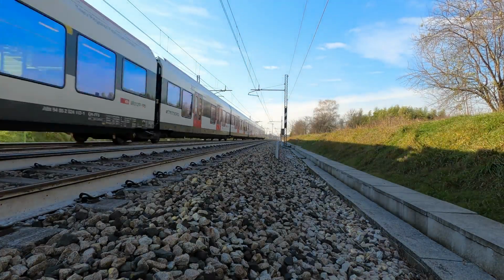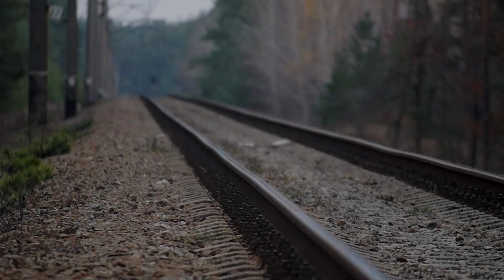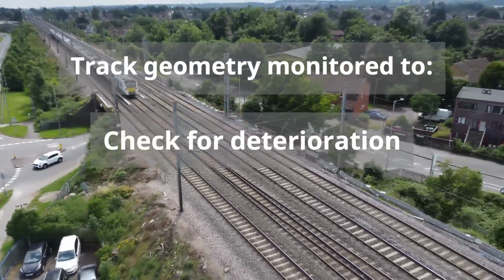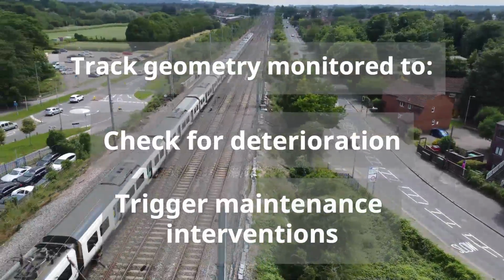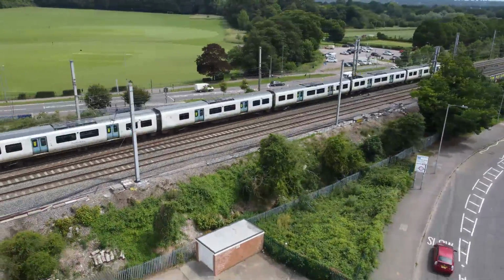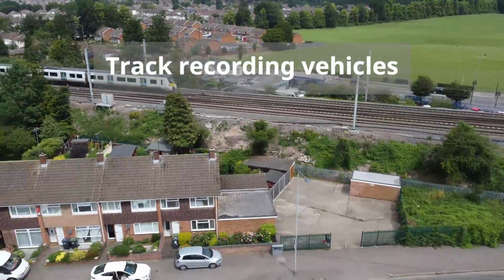Once the track has been designed and installed, that is not the end of the story. It then needs to be monitored and inspected as it's used by trains. It is inspected throughout its life to check for deterioration and to trigger maintenance to ensure it is safe for trains to use. In the UK, a special fleet of trains, known as track recording vehicles, are used to inspect the geometry of the majority of the track.